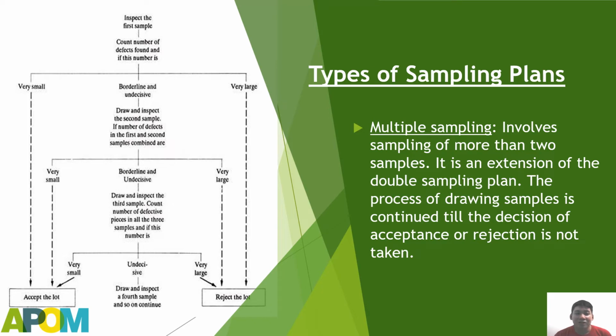New methods which simplify multiple sampling, such as automatic sampling boxes, may result in greatly improved efficiency in administering multiple sampling plans. Selecting the type of sampling plan is dependent on the cost of collecting a sample and testing it. If the cost is high, the single sampling is preferred.